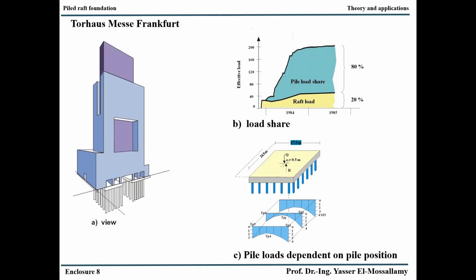And they have applied a lot of measurements, but what they have measured was actually very interesting. They said we apply piled raft foundation. That means the piles take only part of the load, but what we measure is actually that the piles take more than 80% of the load, and only 20% of the load is taken by the raft. And this 20% is more or less actually the own weight of the raft.